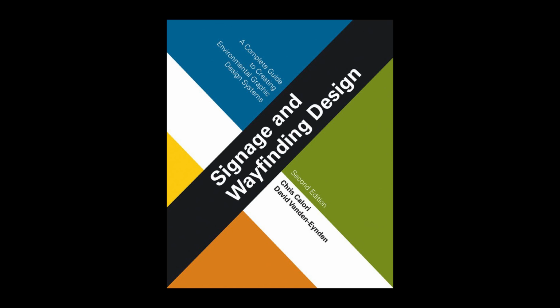and Corten and other weathering steels are specifically manufactured to oxidize to a reddish brown naturally over time in exterior environments without losing their strength and without extensive surface flaking. All patinas and oxide coatings conform to complex shapes, particularly if applied under controlled versus natural conditions. Gloss levels vary with the base material, process, and any additional top coating used over the oxidized coating.